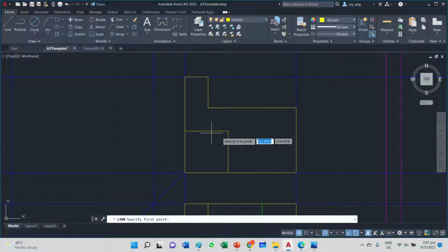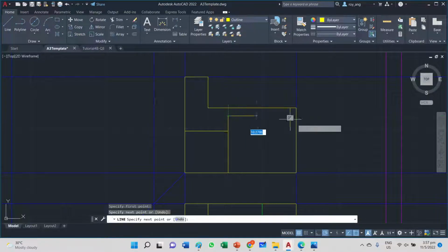The next thing is that you know it goes up this way. Once that's done, if you look at the hidden lines, I don't know how high it goes up. The hidden line comes from somewhere in the middle. The countersunk hole now. Right? And I can copy it, using the copy command. A line that goes across. And I'll select all the lines. Again, we do not know how far across it goes, and where it stops. Right. Right click to accept.